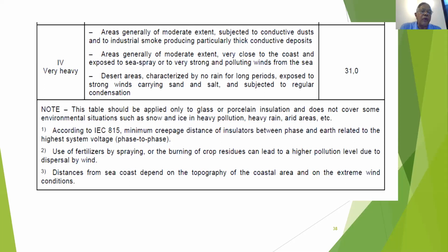If you take 132 kV, you have to use 145, that is the system highest voltage, the maximum voltage.